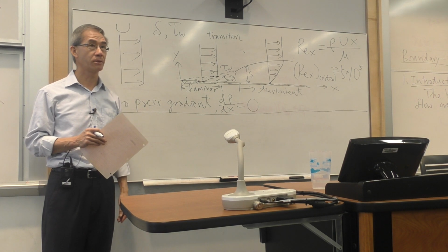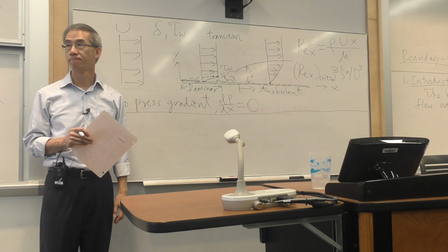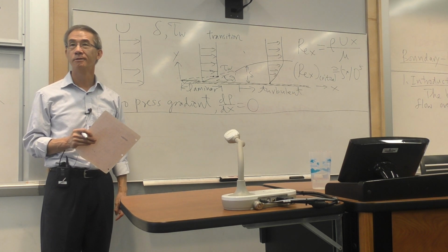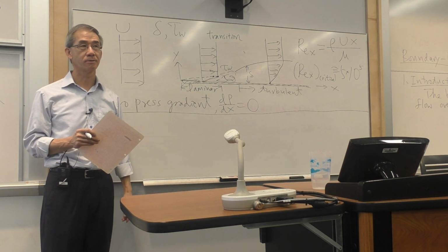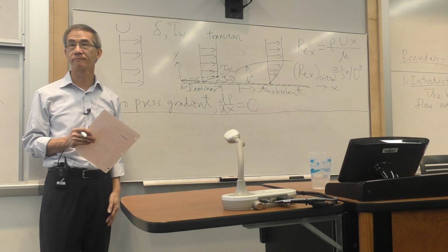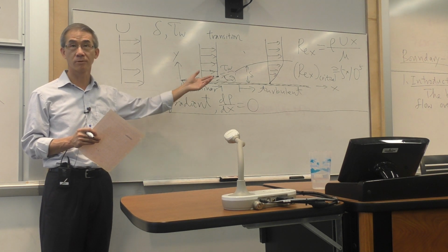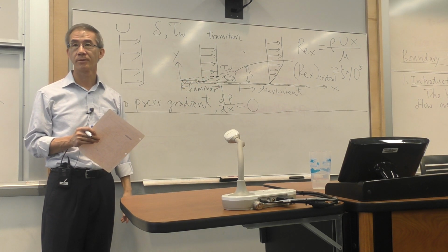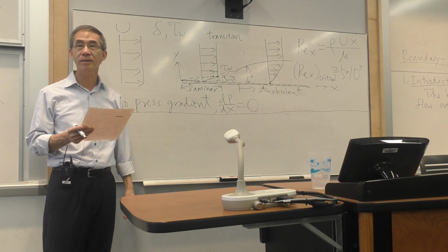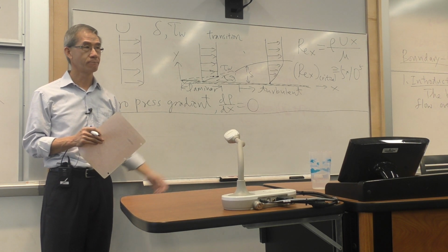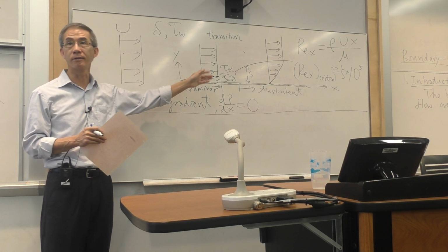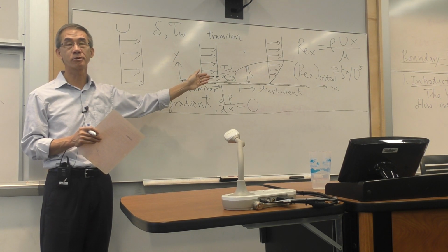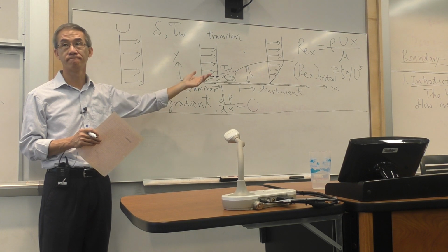How many equations do you have at your disposal up to now? The same question I asked you before test 2. This is no different. This is now just adding a viscous effect. What other equation will you put down to have a hope? I'm not asking you to do it, I'm just asking for the direction. Momentum, clearly. Momentum equation in x and y, but not Euler's differential equation of motion, because that's for inviscid flow.